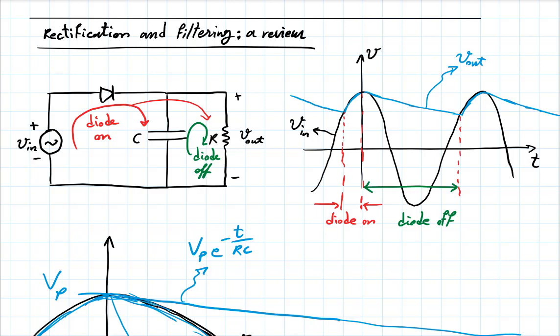So it has the real characteristics. Qualitatively, how does the behavior of the circuit change? If the diode is not ideal, let's start going through those different models of the diode that we had. We had the super simple one. In the forward mode, there was 0 voltage drop. It didn't take any voltage across the diode, and it could allow any positive current. Right? That's what we used here.